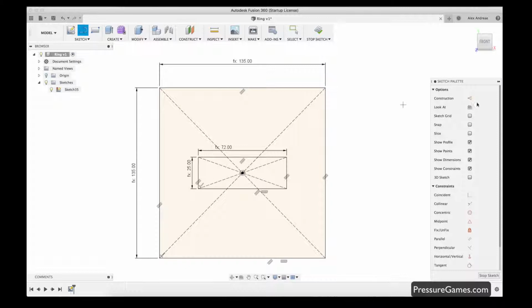For this, we're going to create a construction line. We're going to have 5 buttons, so there's not a perpendicular line that we're going to be able to use. We need to create the line for where the buttons are going to start. So I say we're going to start right here. And for this, I am just going to hard code a number in because, again, this is a construction line. It doesn't really matter. But we're going to say it's 100 millimeters long just to make sure it's long enough.